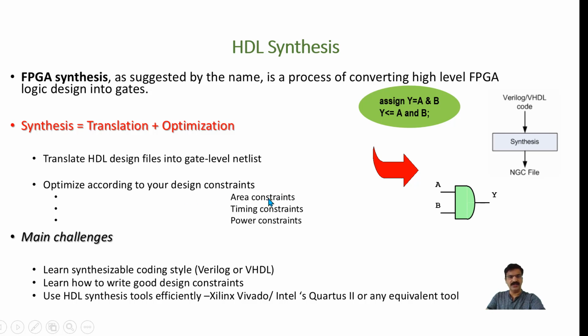Optimize the design according to the area constraints, timing constraints, and power constraints. What are the main challenges? Learn synthesizable coding style in Verilog and VHDL. There are a lot of unsynthesizable constructs in Verilog and VHDL which you should never use if you want to go and synthesize the design.